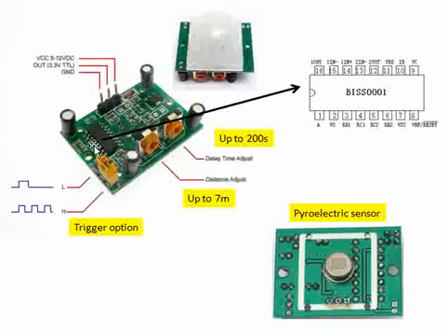and it produces the desired output. If you see here, there are three pins mainly which we interface to the outside. One is ground, and one is supply, which can be 5 to 12 volts. Some PIR sensors can support up to 5 to 20 volts as well. Ultimately you have a regulator on board which converts this into the lower voltage supported by the BISS0001.